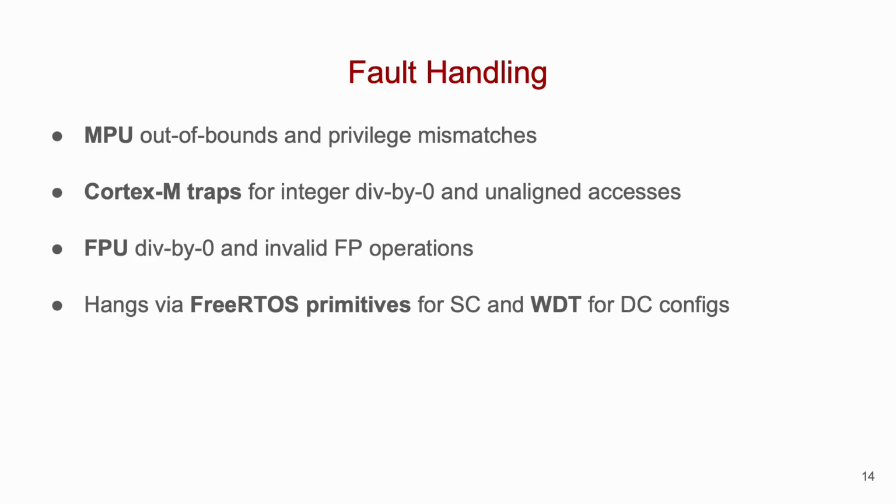To detect hangs, it uses FreeRTOS primitives when in single core configuration and the watchdog timer for dual core configurations. Then it detects exceptions via exit codes.